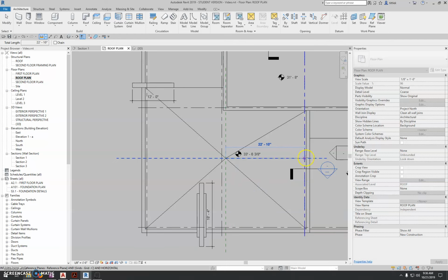So this is the longer dimension of the two, which means that we're going to have more slope here. And our slope is minimum 1/4 inch per foot. We can go above that, and if we go with our worst case scenario, which in this case is the 23 feet 4, we know if we slope this by that much, this piece will slope even more than 1/4 inch per foot because it doesn't have as long of a run.